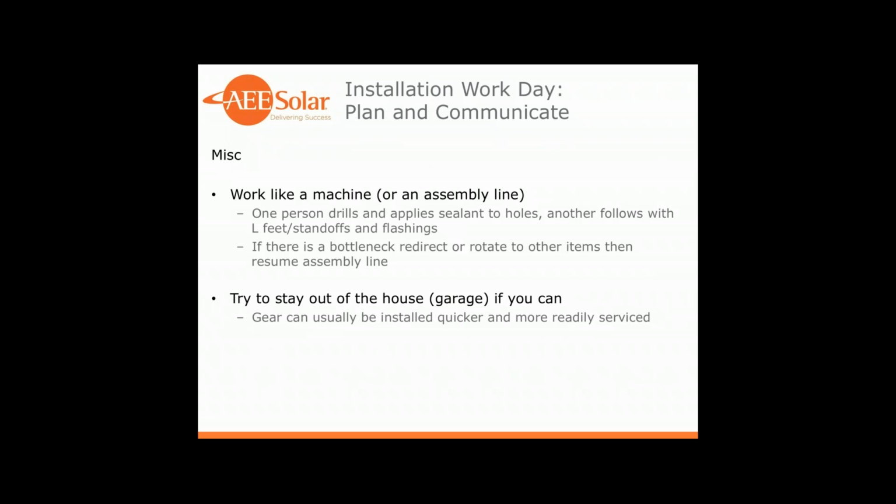So another concept to keep in mind is, let's work like an assembly line. You'll have one person taking the lead, they'll drill and apply sealant, and you'll have another person following them with the L-feet, standoffs, flashings, the rest of the attachment hardware. And what you can do with this assembly line concept is, anytime there's a slower step, you can either have more people do that process, or you can immediately have the person following them jump to another task until the person in the lead has gotten ahead or caught up again.